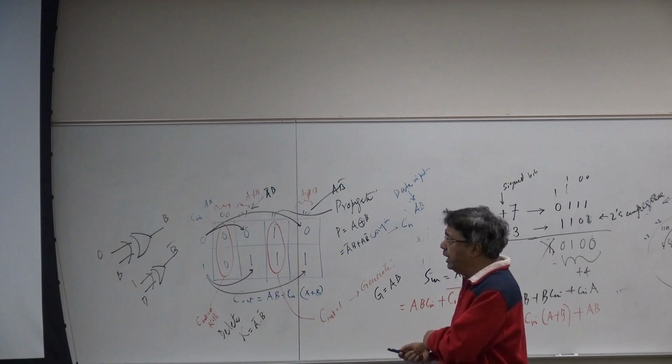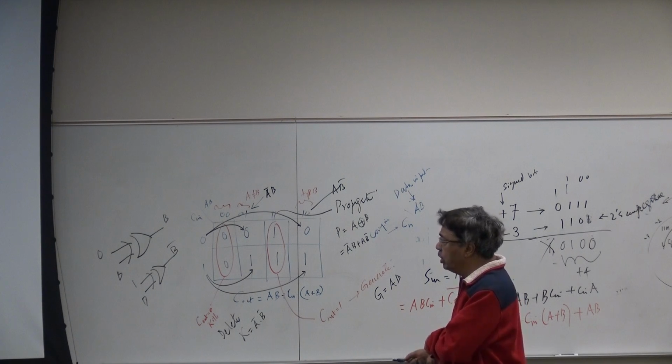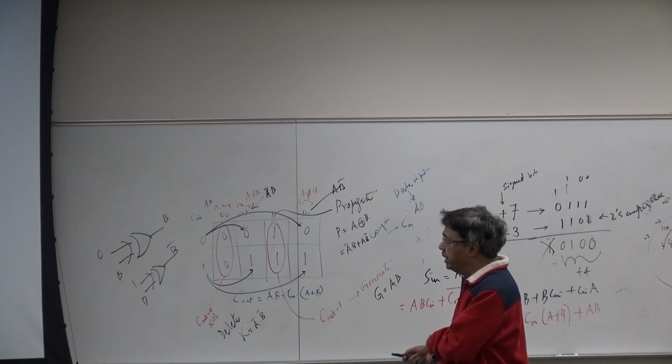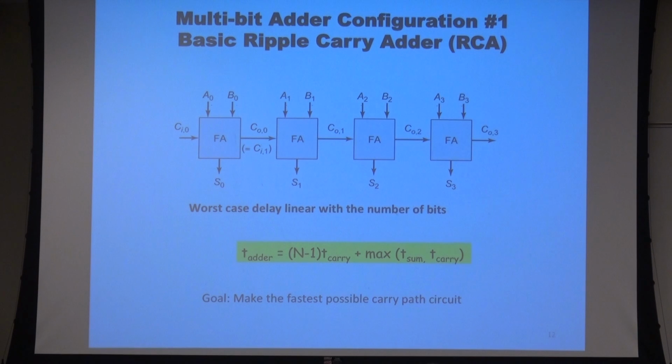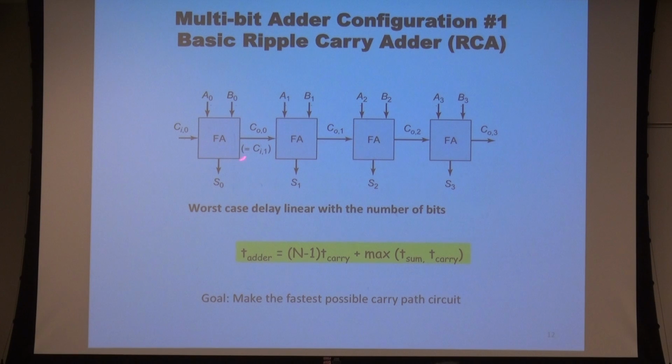So if I increase the number of full adders, the number of stages, the delay increases linearly, because this is a constant term. This is the reason why we don't make a very long carry chain. Typically, we restrict to 4 bits of ripple carry, and then we use other ways to improve the performance. Okay, so keep this in mind.